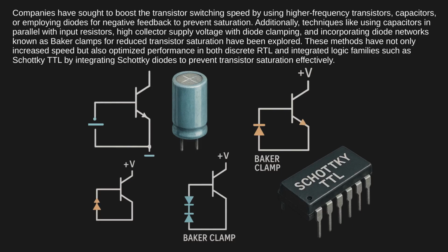These methods have not only increased speed but also optimized performance in both discrete RTL and integrated logic families, such as Schottky TTL, by integrating Schottky diodes to prevent transistor saturation effectively.